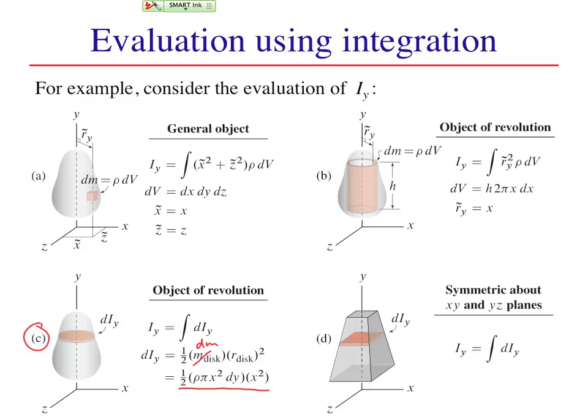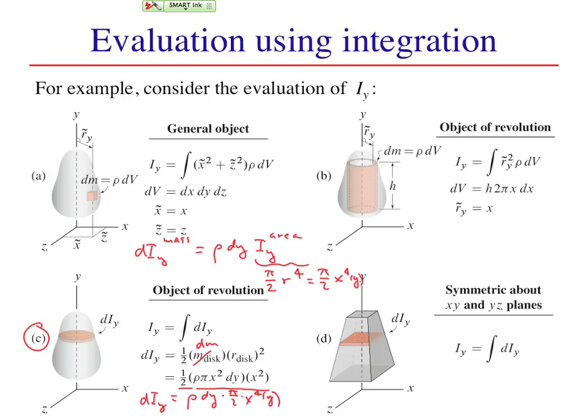So now we have an increment of mass moment equals mass density times infinitesimal thickness times area moment about the y-axis. But we had previously shown that for a circle, this was pi over 2 times the radius of the circle to the fourth. In this case, r is just our x of y, but this is exactly the same as what we have here.